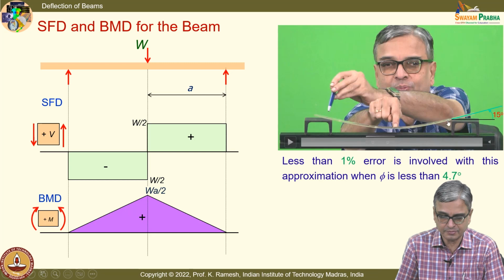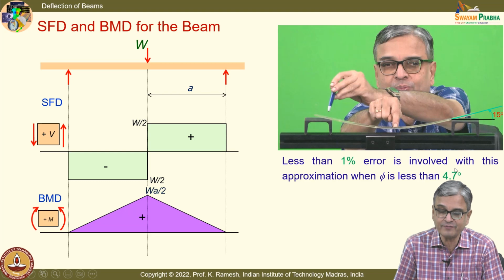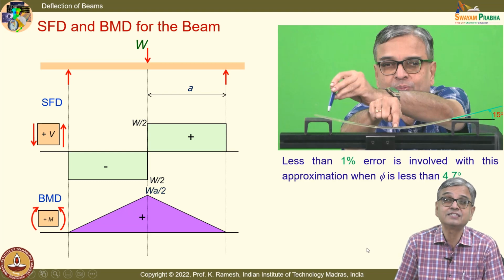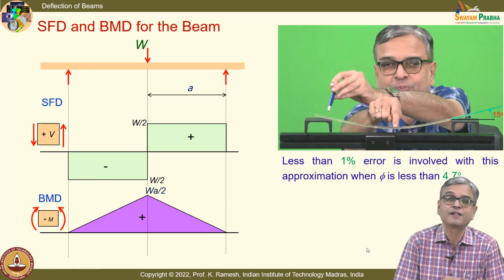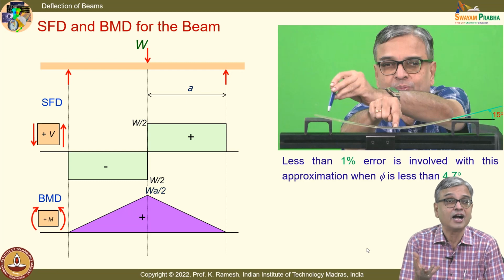I have shown this and I have also measured this angle, fine, and this was turning out to be 15 degrees. I said that these equations are applicable only within 5 degrees as a slope. This is just to re-emphasize, when I perform the experiment, the deformations are extremely large intentionally for you to visualize how to look at bending as a whole.